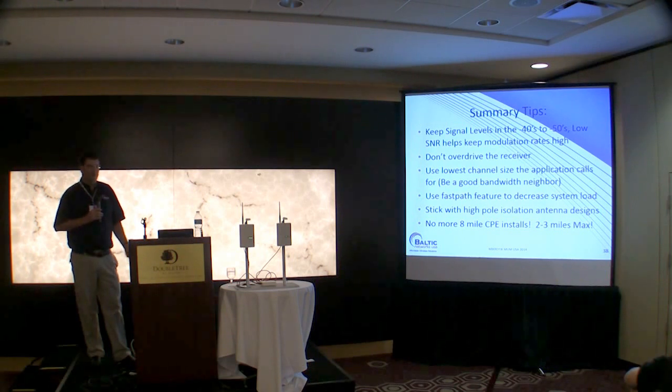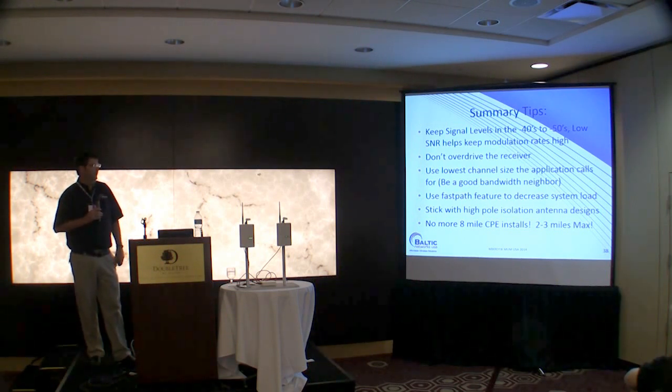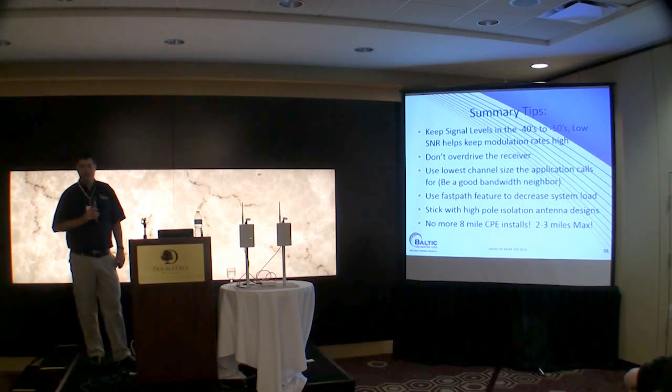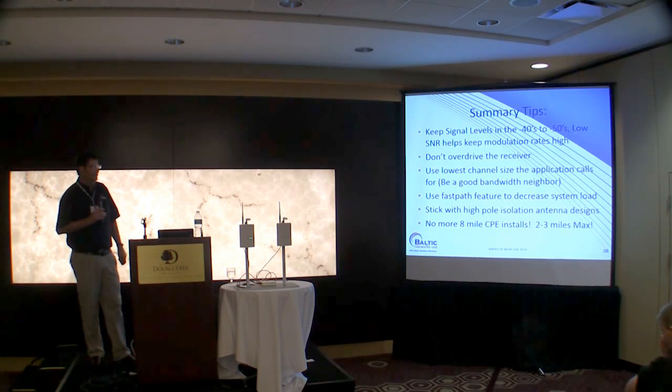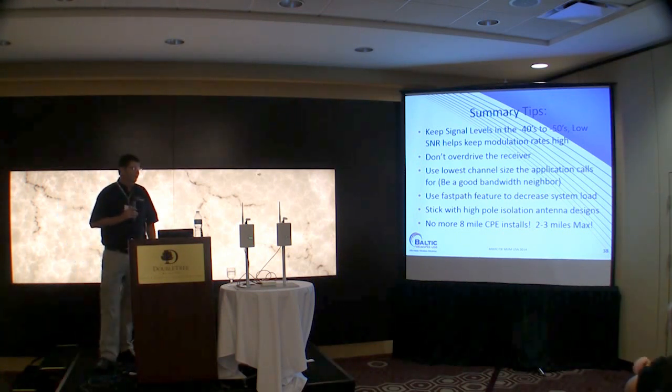On the CPU, you'll get better performance out of it. And look for those high isolation port antennas. You'll have a better setup overall. Finally, for your rural folks, 8-mile CPE installs aren't going to work really well with this technology. You're going to want to keep it down to 2 to 3 miles if you're doing multi-point.